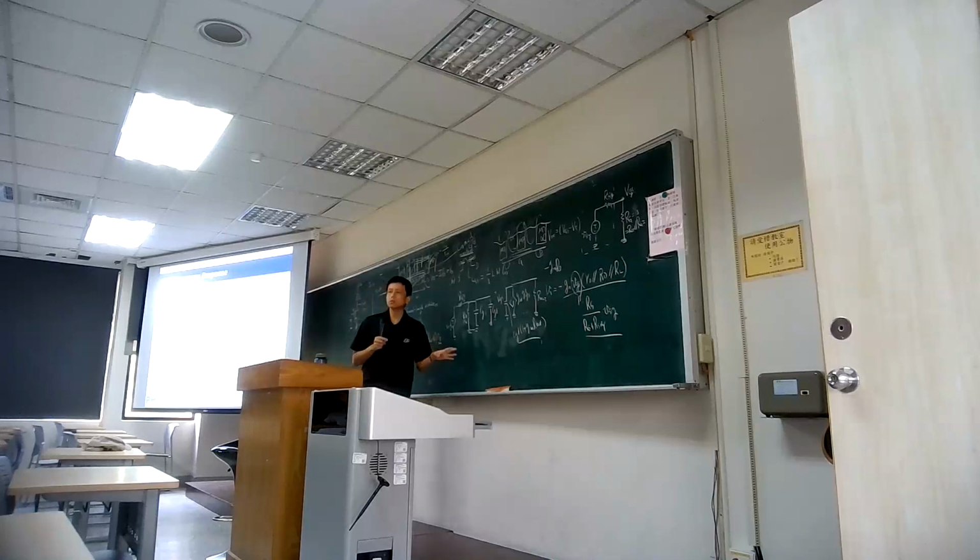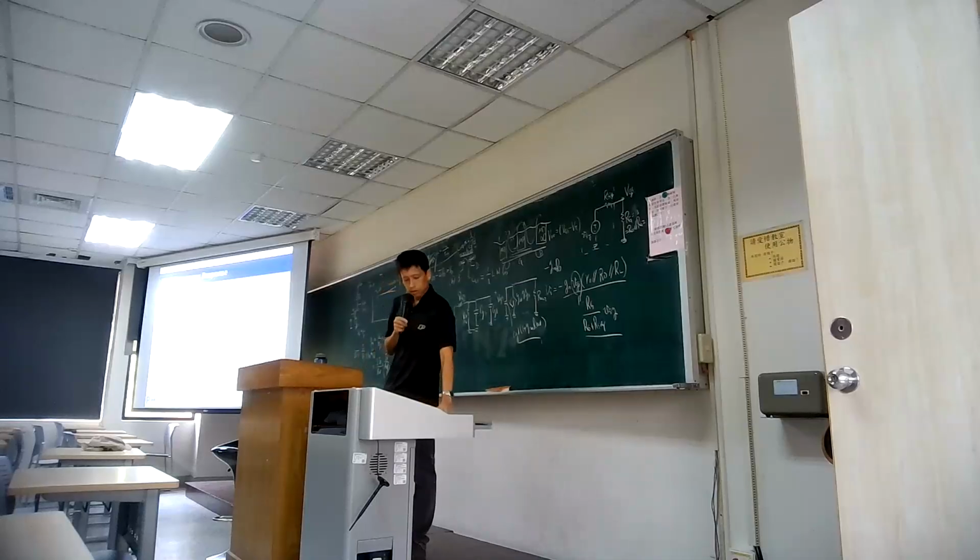This one I will not show you in the final. Maybe all of that's already been done. So there will be nothing regarding it on the final, but I still need you to understand. So we separate the capacitance, and you can see this capacitance is just like an RC time constant. So in order to calculate the high frequency response in your transistor, you need to separate this capacitor and see how it impacts your high frequency response.